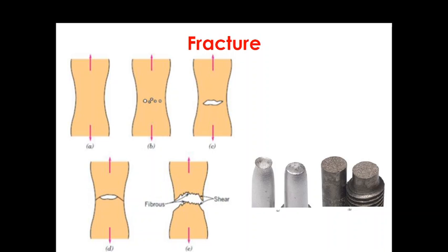So sometimes a fracture having this characteristic surface contour is termed a cup-cone fracture, because one of the mating surfaces is in the form of a cup and the other like a cone. This can be shown here, cup-cone fracture. So cup-cone fracture is the indication of a ductile fracture, whereas this figure B is a brittle type fracture, completely flat, with no deformation at all. And how a cup-cone fracture occurs is evidenced here in these 5 figures.